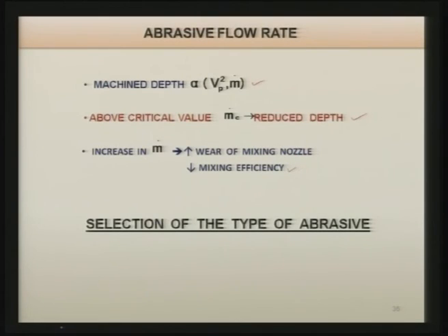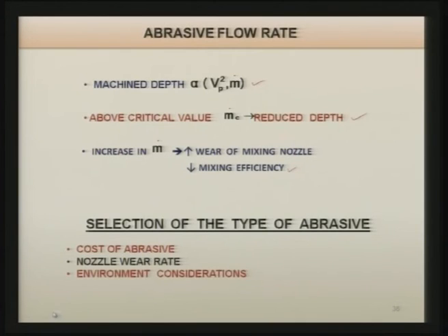Selection of the type of the abrasive depends on the cost of the abrasive, nozzle wear rate, environment considerations and machining rate, and finally, it is also affected by the particle strength. Let us see the effect of abrasive flow rate.